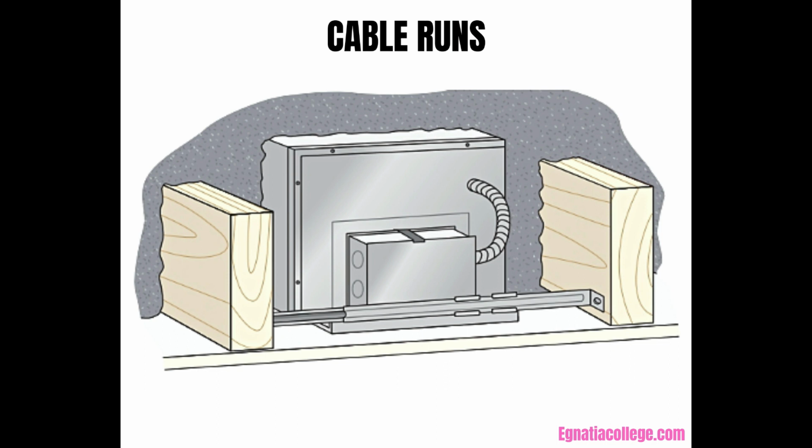The grouping of outlets into circuits must satisfy the requirements of the CEC, local building codes, good wiring practices, and common sense. A good wiring practice is to divide all loads as evenly as possible among the circuits. Ensure that no more than 12 outlets are placed on a 2-wire circuit. Keep cable runs as short as possible. Use boxes that have adequate space for conductors and devices. See Rules 8-104 and 8-304.